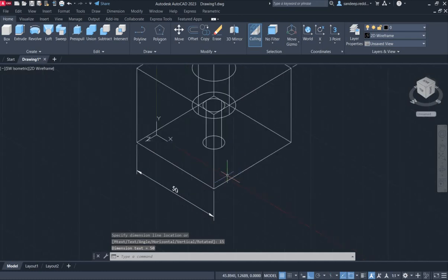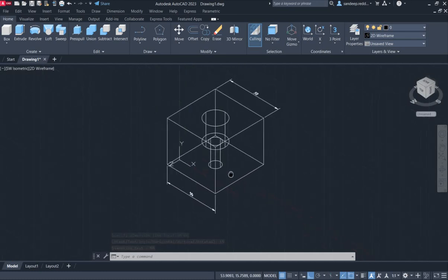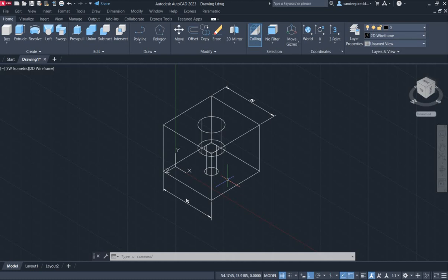So that is how dimensioning works for 3D objects. Just a slight difference when compared to dimensioning 2D objects, but it means the same thing, because in 2D your drawings were contained within the XY plane, hence it was very straightforward to dimension. So while dimensioning, always remember to check whether the side or surface you are dimensioning is within the XY plane of the UCS.